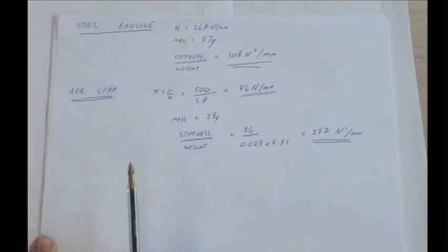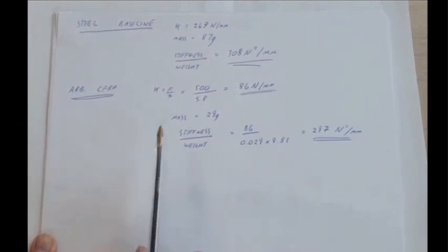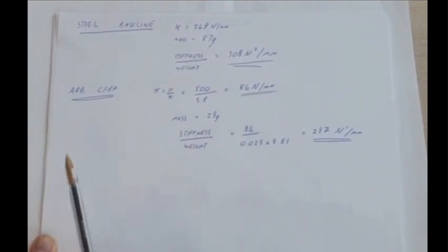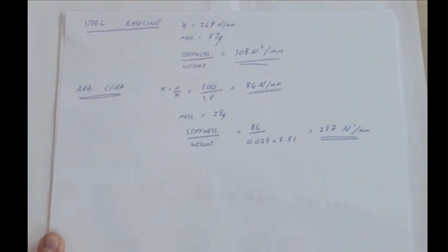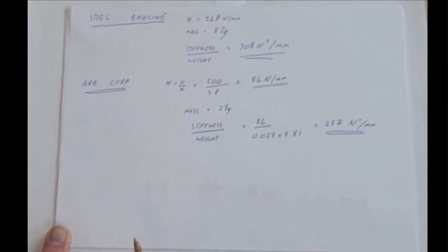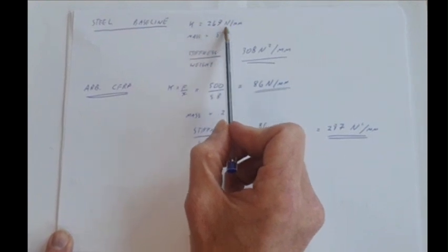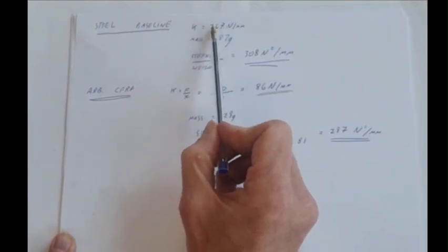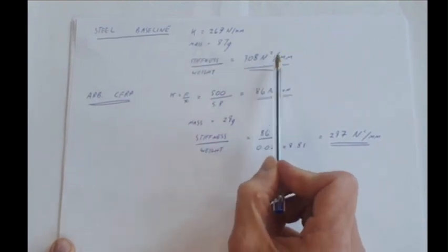Okay, so what we're going to do now is, instead of arbitrarily laying that up with 5 plies at -90, 5 plies at -45, 5 plies at 0, and so on, we're actually going to define variables, objectives, constraints within our structure to define how many plies we need in each layer to give us the same stiffness. This stiffness here was our steel structure. Okay, and hopefully by doing that we'll have a much lower mass, so therefore our stiffness to weight ratio will be better.